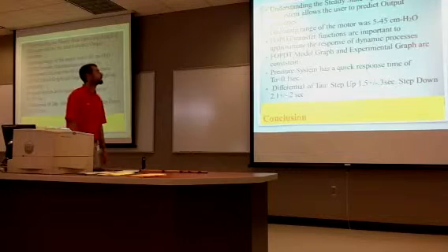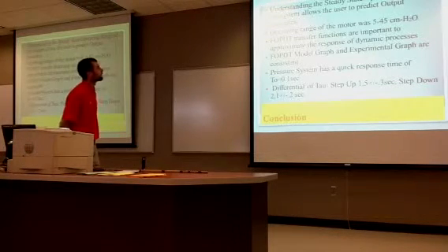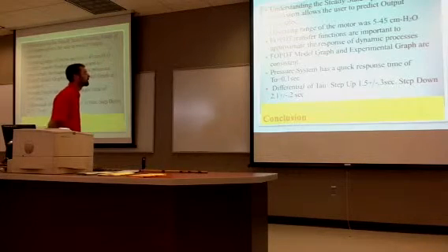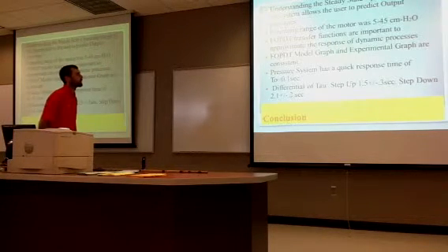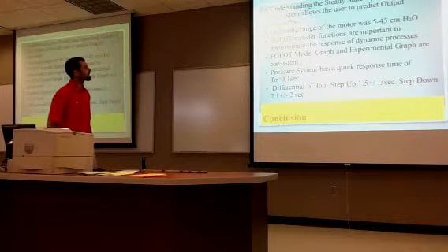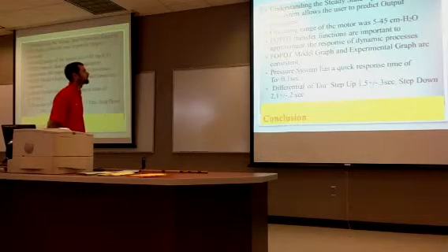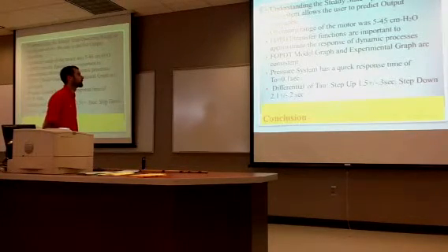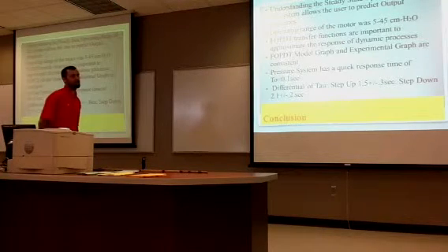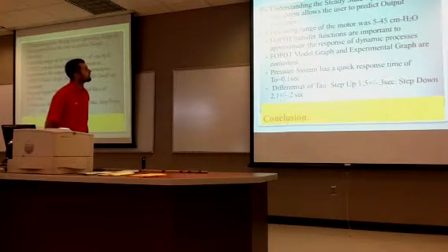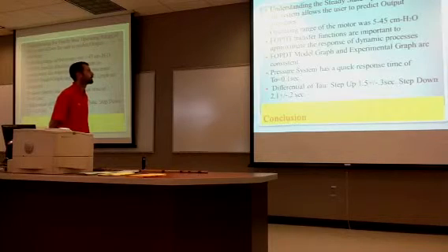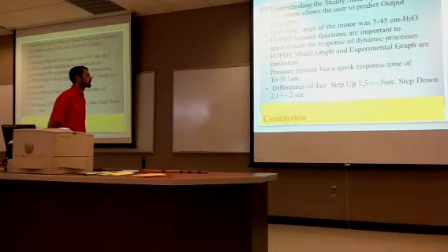Some conclusions are we were able to understand our operating ranges and predict outputs. Our full operating range was 5 to 45 centimeters of H2O. On the FOPDT, the transfer functions are important for approximation and response to dynamic processes. We were able to use that to model our graphs and do experimental graphs to show the consistency.